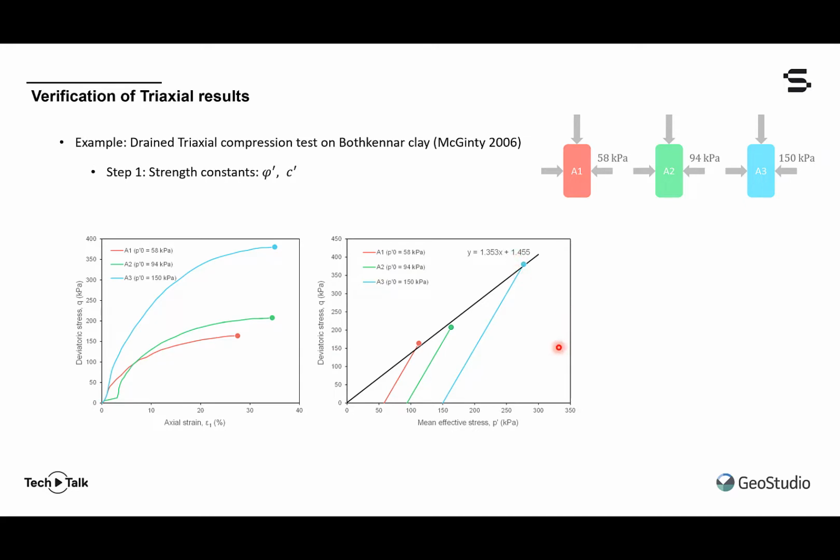And so when we transform that into our shear-normal space with which we are accustomed, we can take tan beta and alpha and convert that using the formula shown previously to an effective friction angle and effective cohesion of 33.5 degrees and 0.712 kilopascals.